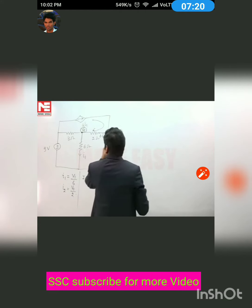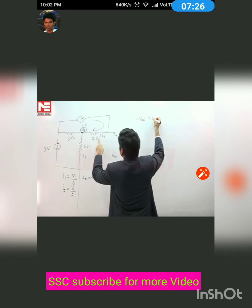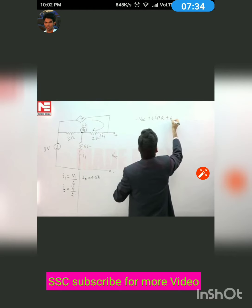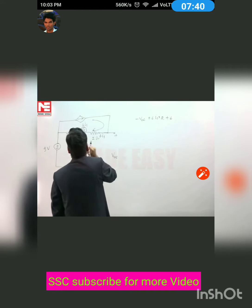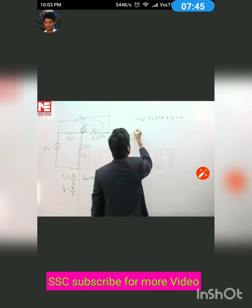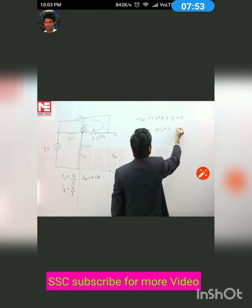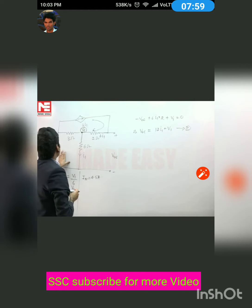VOC can be written as minus VOC plus 6 I1 into 2 plus 6 I1 plus V1 directly. This V1 is equal to 0. So VOC is equal to 12 I1 plus V1, equation 2. Now we have to calculate I1 and V1.